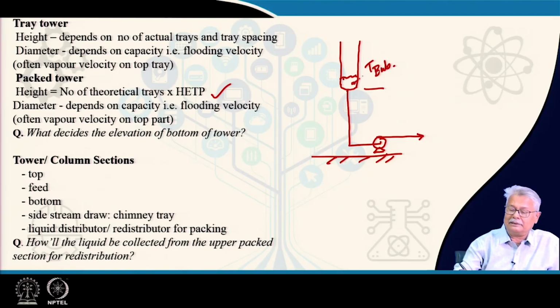That means this temperature is the bubble temperature of the liquid. So naturally, if you send it to any pump, a boiling liquid going to the pump will immediately vaporize and vapor lock your pump. So you cannot do it directly.